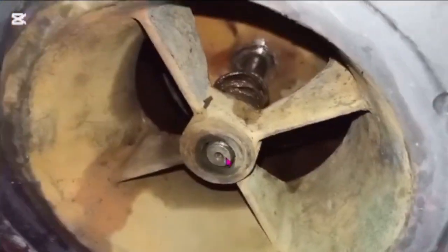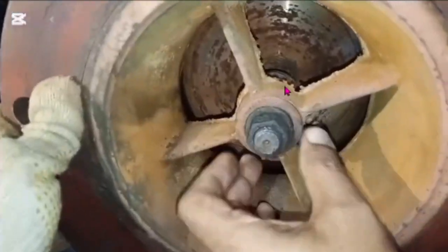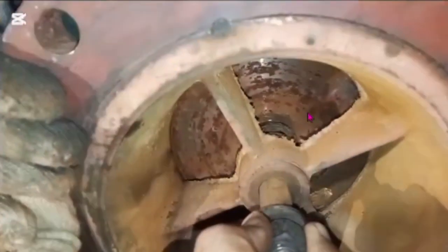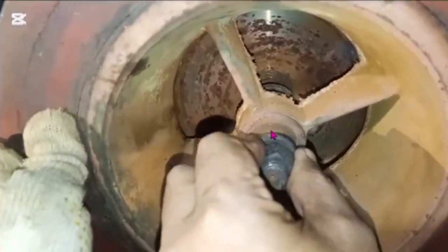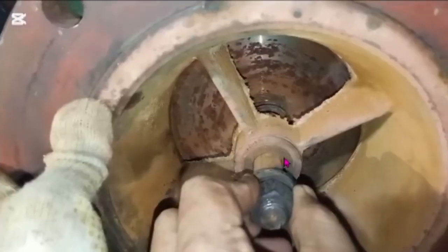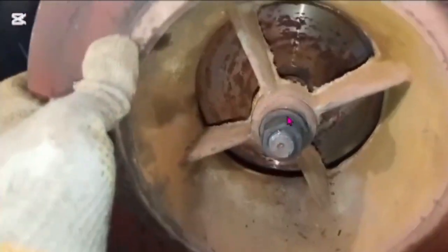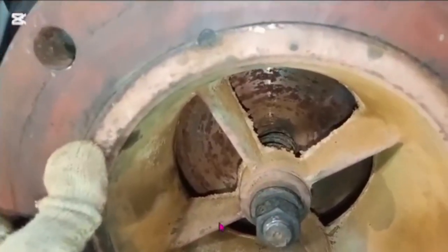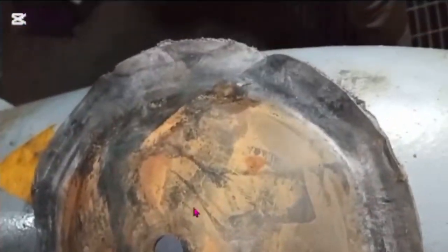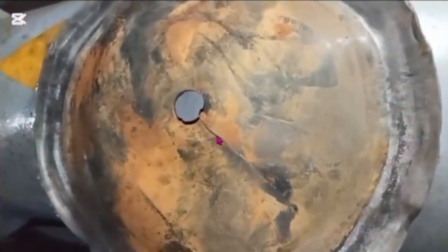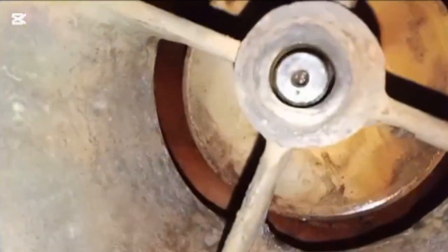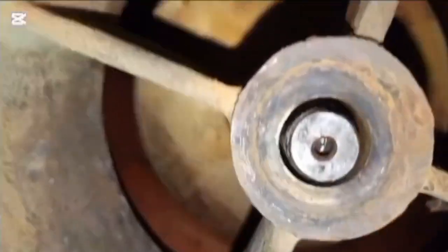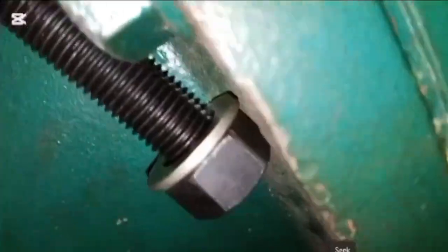Here this is the ejector unit. This is the spring. One of the springs was damaged. The spring was not functioning. We also changed this spring and checked whether the spring is functioning or not. Here we need to set the diaphragm. Initially we only made a scratch and then connected this diaphragm to the ejector and followed. The vacuum was only 22 to 25 kPa.